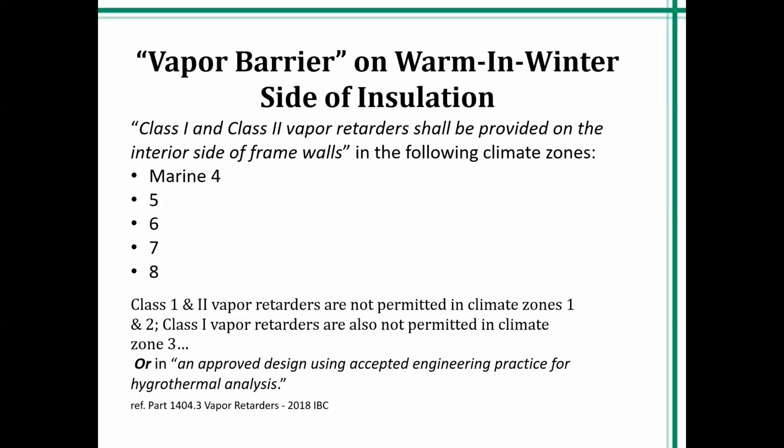This building was about 6 months into service, and the occupants, this was an insurance company, ironically, along the exterior wall noted that every spring, the bottom 6-8 inches of the exterior wall would become notably wet and would literally be bleeding water into the building's interior. And it wasn't until they consulted with this engineering firm, Grand Rapids, who investigated it and found that they did in fact have a double vapor barrier.